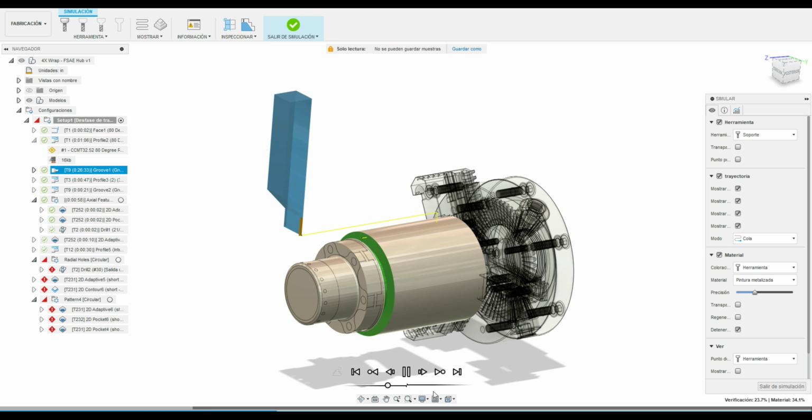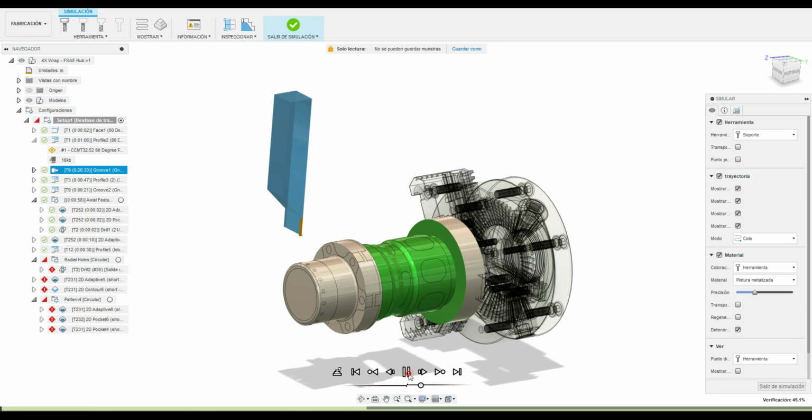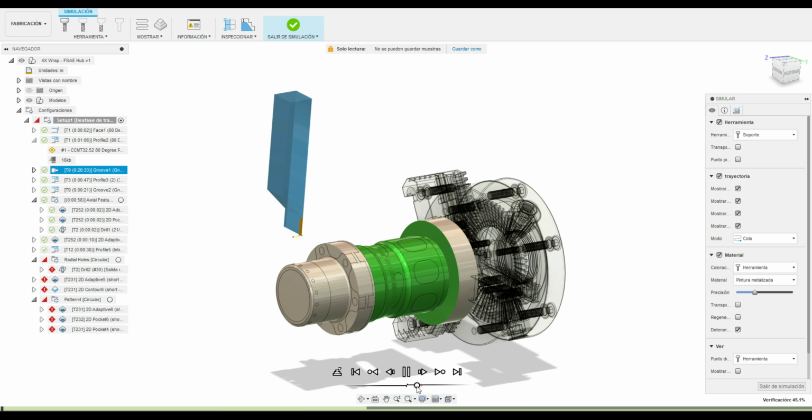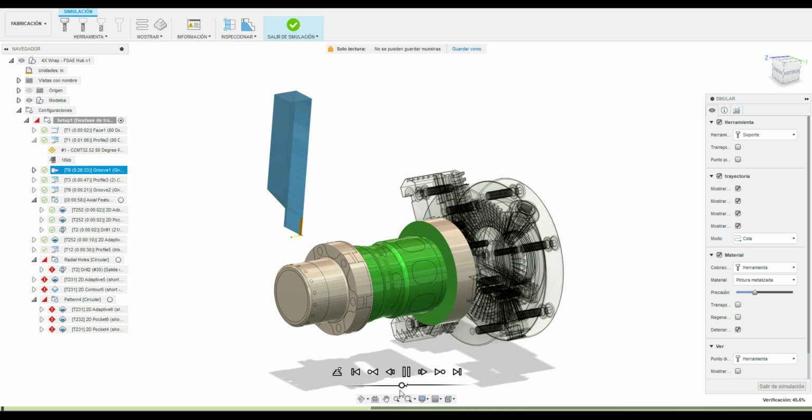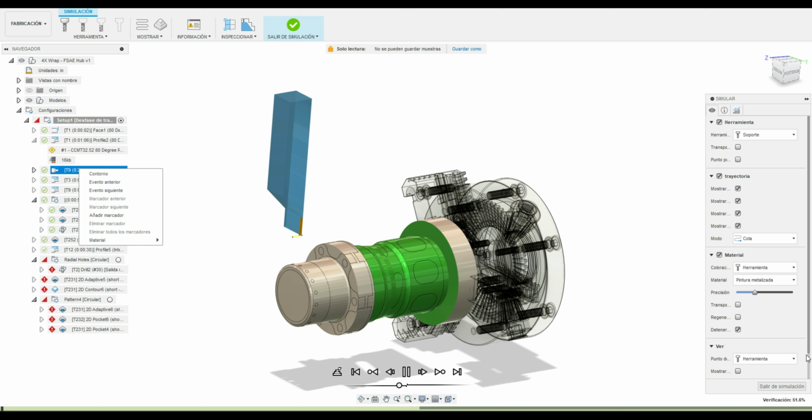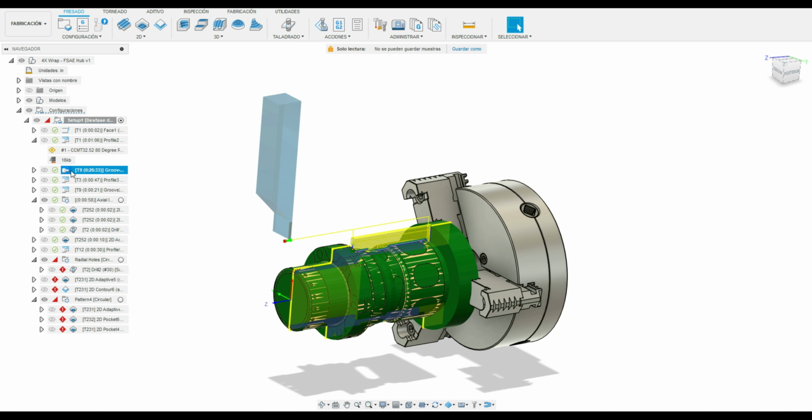Fusion 360's toolpath simulation allows us to visualize and verify each operation before machining begins. Here, we analyze potential collisions, gouges, or overcuts, and confirm safe retract movements. The color-coded material removal gives a real-time view of how the part evolves layer by layer. This predictive analysis reduces machine downtime and guarantees that the physical machining process is both safe and efficient. Every verified operation here translates directly into production confidence.